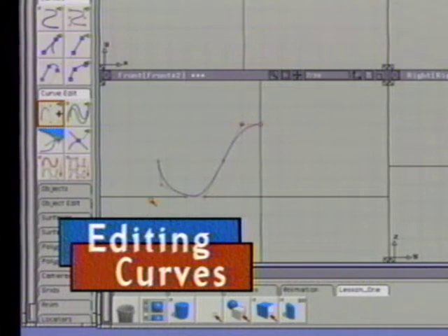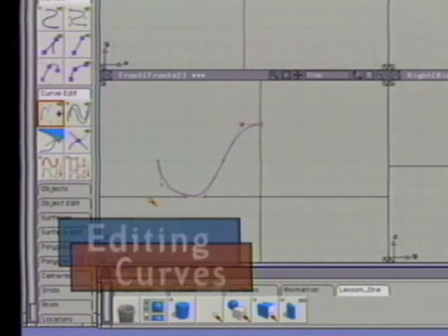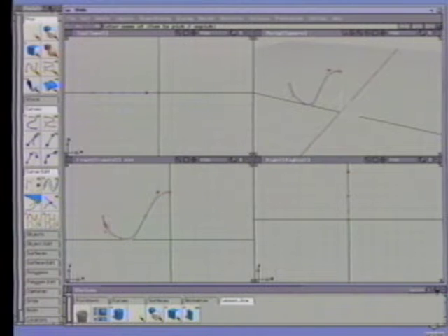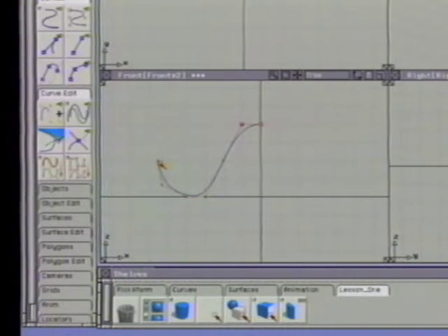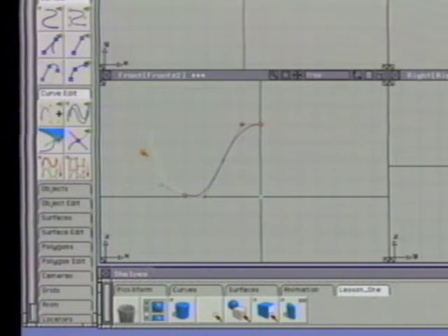Generally, you can edit the shape of a curve by modifying the position of the CVs. To refine the shape of the sombrero profile, you can pick and move the 2 end CVs. Select Point Types CV. In the front window, click on the End CV. Select X-Form Move. Click Drag to move the CV around the front window.